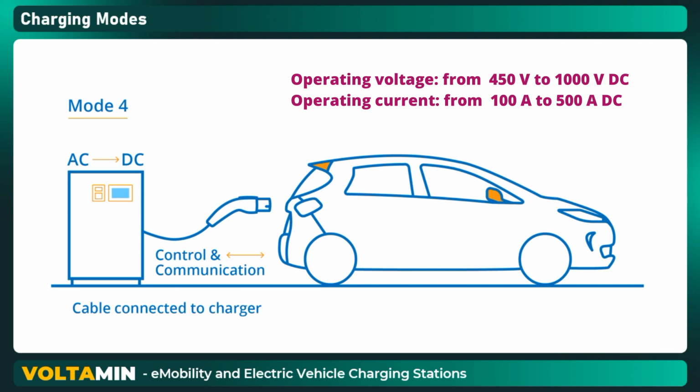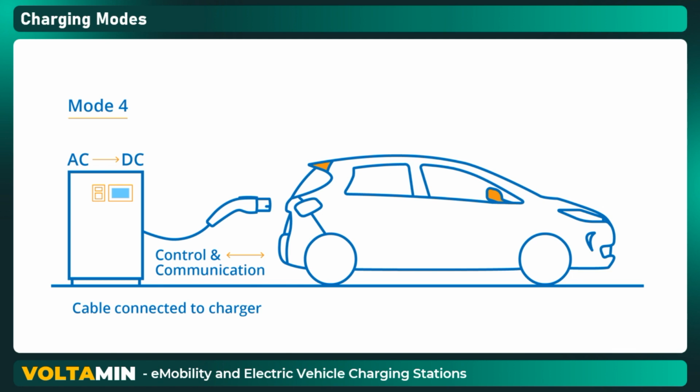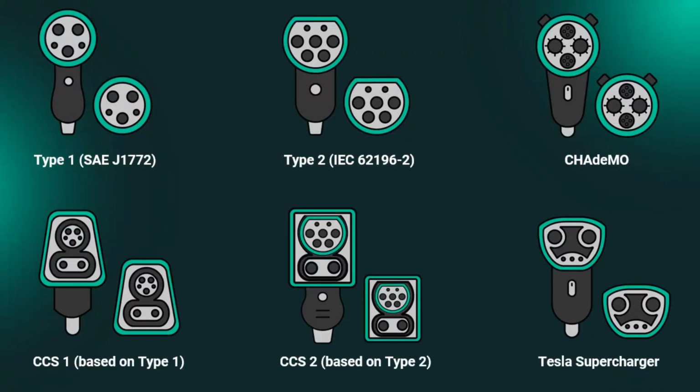In Mode 2, 3 and 4 the addition of a control pilot inside the charging station enables communication between the vehicle and the charging equipment through standard protocols. It also allows the implementation of control functions, such as verification that the electric vehicle is correctly connected to the EV supply equipment, continuous verification of the integrity of the protective conductor, energization and de-energization of the power supply, transmission of information about the maximum permitted current to draw, charging plugs and connectors.